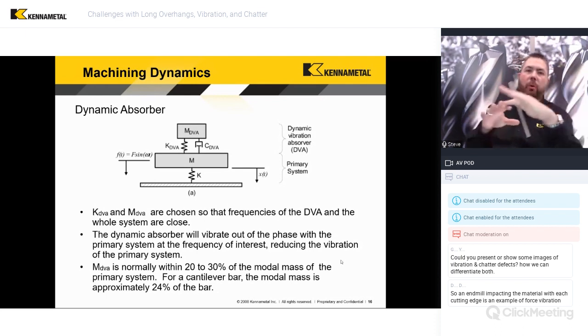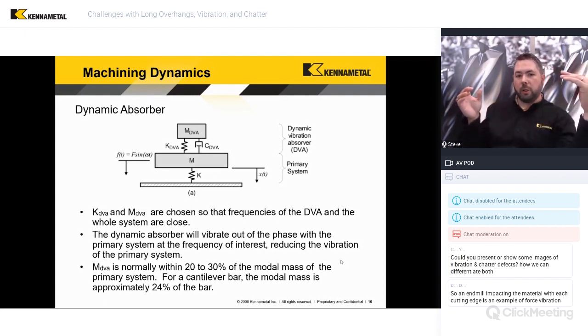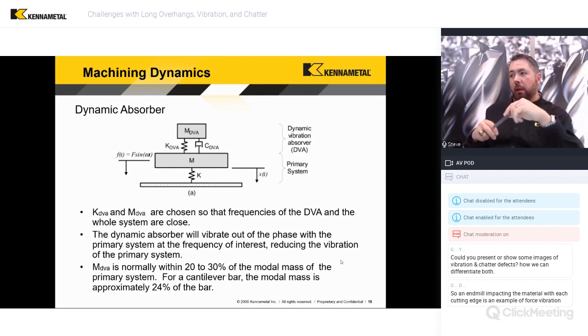If we started to break this down into some basic equations of motion, we would be looking at the spring element going with displacement, and the damping element going against the velocity, so multiplied with the velocity that the mass is moving at. What does that really mean? The easiest way I can explain it is to think about a shock absorber in a car. A shock absorber is usually gas-filled or liquid-filled, and you're really relying on friction, usually Coulomb friction. With increased velocity, we'll have increased friction, increased drag. That gives us a stronger response against the motion as the velocity increases.